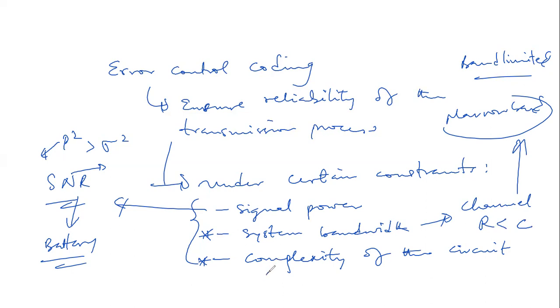So we now come to the complexity. The circuit that we need to arrive at this system should not be altogether complicated. But should we desire to correct errors beyond 1 bit, such as burst errors and the like, know that we have to deal with that complexity, because we will now have to move from combinational circuits to sequential circuits.